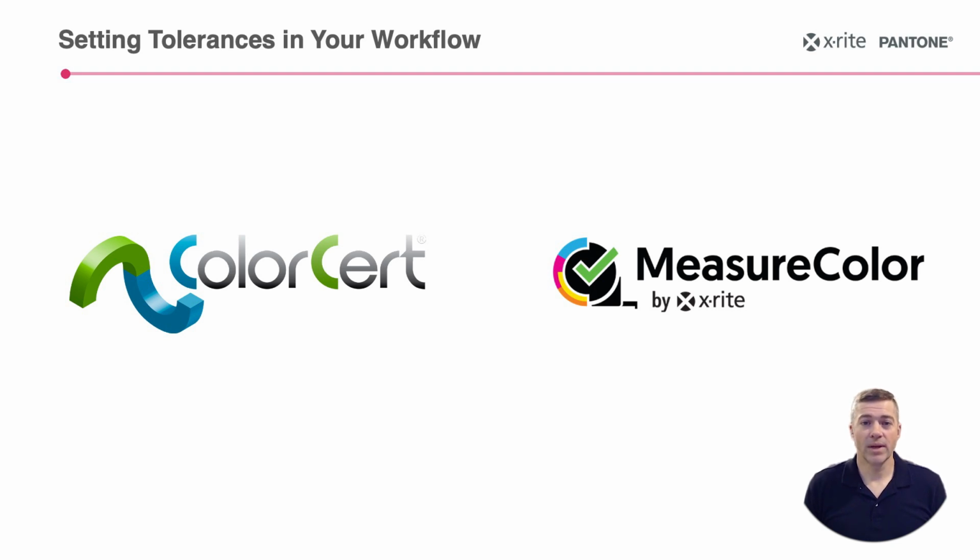In ColorCert QA tools software, there are several ways to configure your color tolerances. For example, you can set a global tolerance that applies to all your color standards for most production work. If a customer has specific tolerance requirements that differ from your standard production settings, you can add their name to the database, associate their colors with their customer name, and define their custom tolerances. Then, during production, selecting that customer's name will ensure that only their colors and corresponding tolerance values are available for measurement, streamlining the process and ensuring accurate compliance with their requirements.